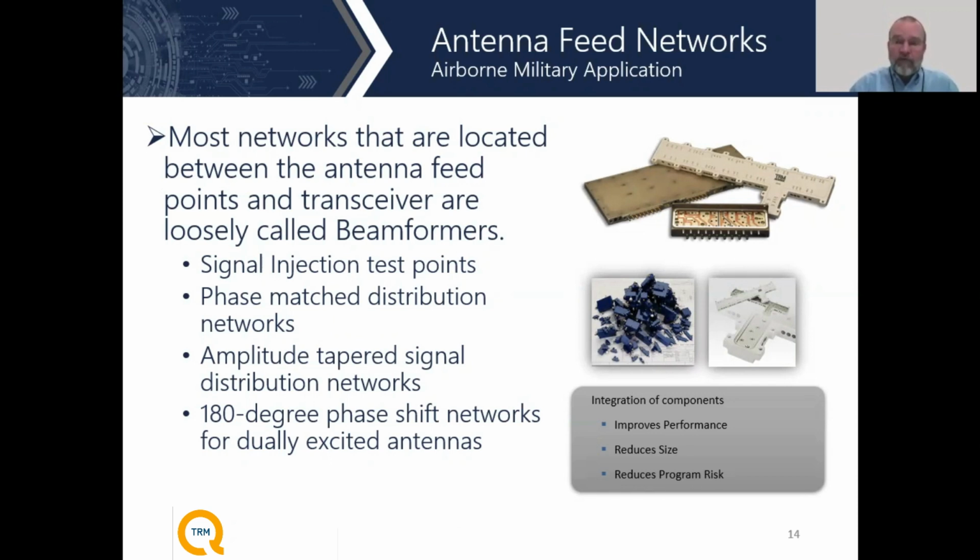So we build quite a few parts for those sorts of applications, and we loosely call those beamformers as well. The other thing we use beamformers for very often is just creating the particular amplitude and phase difference required for specific antenna feeds. Log periodic antennas, for example, do want to have a 180-degree phase shift as part of that infrastructure. We will very often build into our beamformers those sorts of phase shifts, so they become multifunction modules in that way as well.